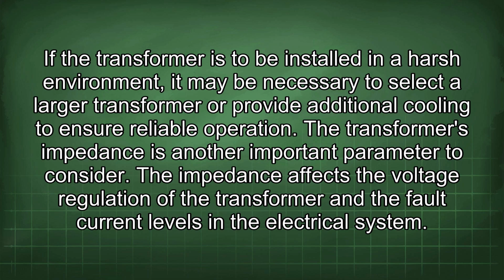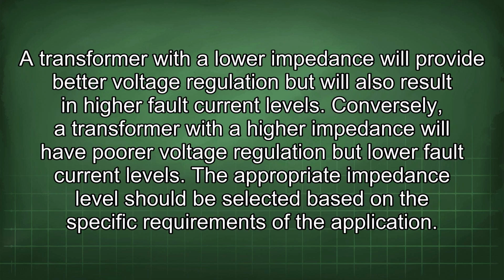The impedance affects the voltage regulation of the transformer and the fault current levels in the electrical system. A transformer with a lower impedance will provide better voltage regulation but will also result in higher fault current levels. Conversely, a transformer with a higher impedance will have poor voltage regulation but lower fault current levels. The appropriate impedance level should be selected based on the specific requirements of the application.